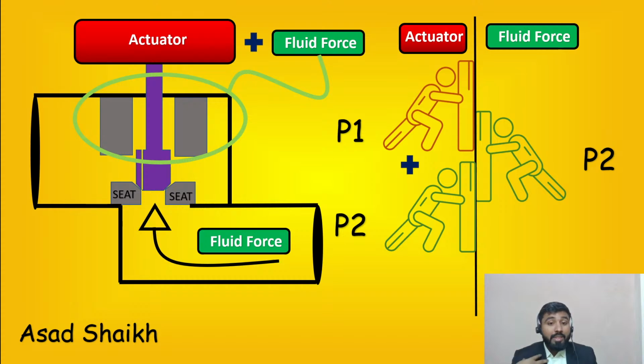I am not saying this for any personal gain, but accidents have happened, for example in the Husky refinery, where, if you remember, the control valve got eroded. The second thing is, because a control valve is continuously in application, the trims get eroded. So there was that slight leak in the control valve. When the equipment was removed, slight air passed into it, which got together with hydrocarbon, and you know what happens when air gets in contact with hydrocarbon.